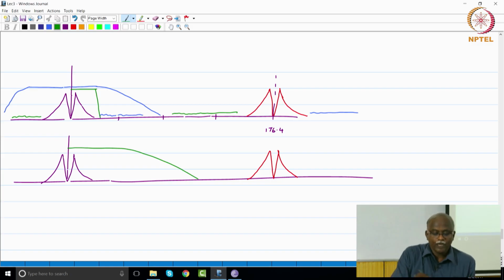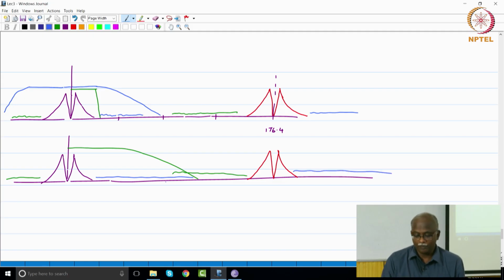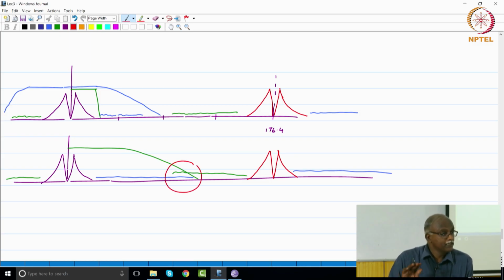It will allow more of the blue to leak, correct, and the green will be present here, and when the copy comes, these two will overlap. See, there is an overlap which previously was not present, but now is present. Okay, is everyone clear with this one? This is aliasing, but has it affected your desired signal?